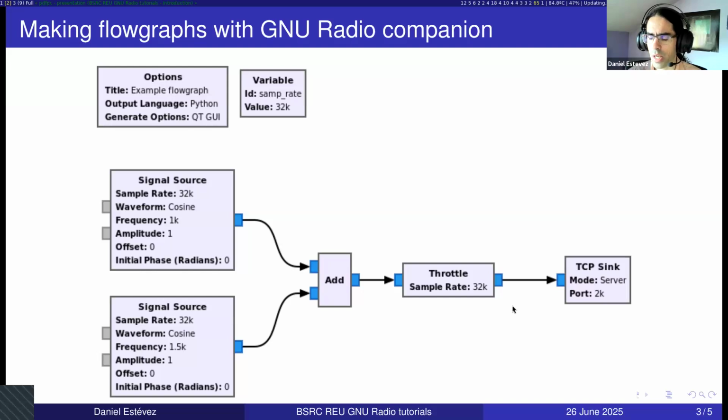So when we use GNU Radio, there are usually 2 main ways of using it. We can either obtain our data from some kind of radio, which supplies the data in real time, and we will do that today. Or we can run in a simulation where there is no physical hardware, and everything is just software running on the computer. So something needs to set the pace of this simulation, because otherwise the computer is going to run things as fast as possible. The simulation is going to use 100% CPU.